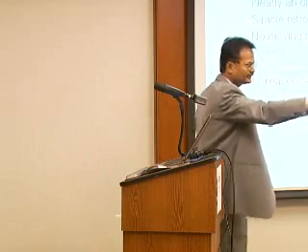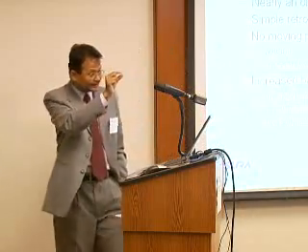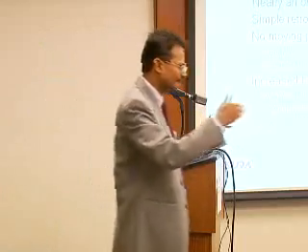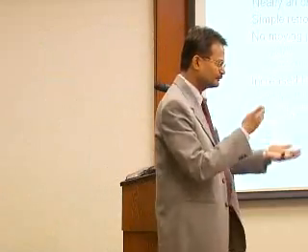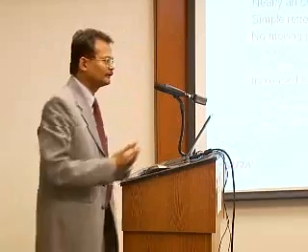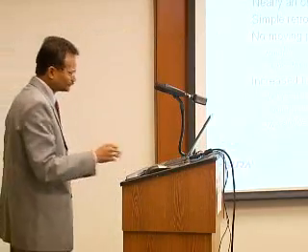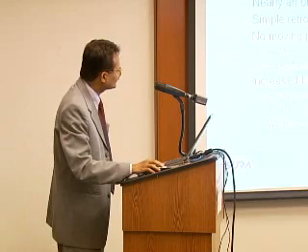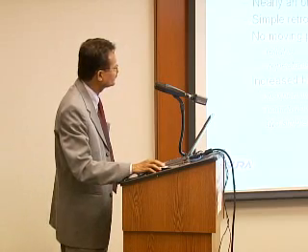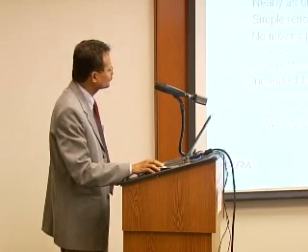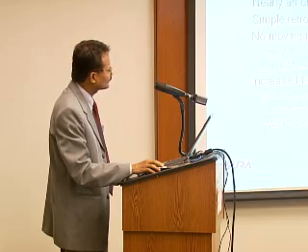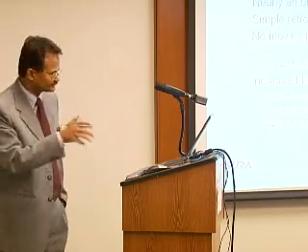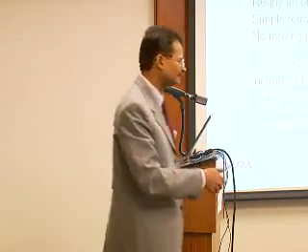We have already designed it. In that chip, we actually have 6 of those spatial demuxes. We are still running through the beta types, trying to figure out which is the best solution for us. So that is the spatial demultiplexer. On the other end, here is our spatial multiplexer. Combine these two and you get output over here. That is a center spot and a second spot around it. And if you want, you can have up to 6 different channels, which we have done and published.